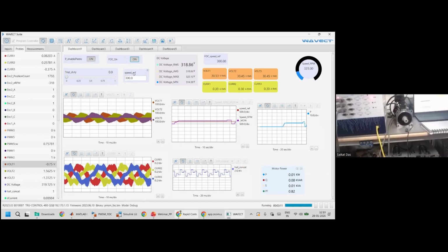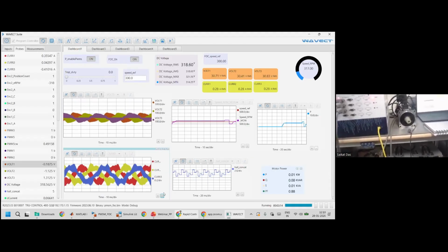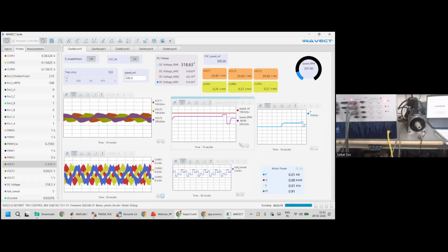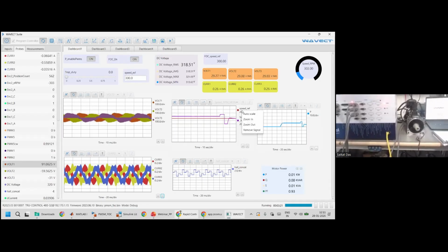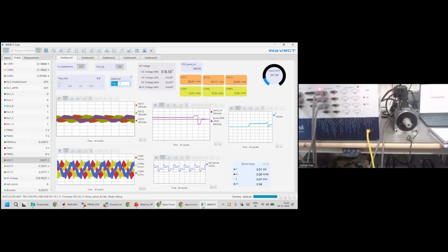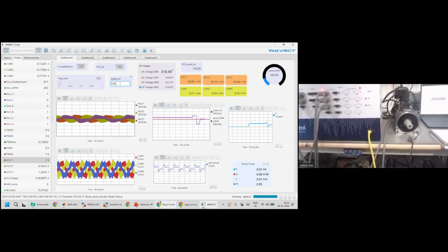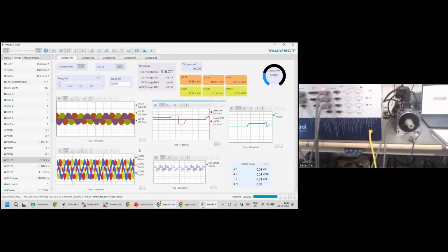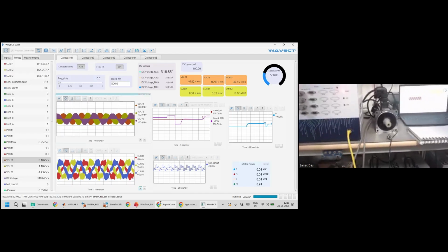So now let me increase the speed of the motor. Now I am entering the input speed of 500 RPM. Based on the 500 RPM, you can see my motor current also increased. That's the motor voltage waveform, and this is the pulse sensor concatenator. Let me run the motor at, let's say, 1500 RPM. Simply click on enter, and you can see whatever the reference speed I entered, the motor is following the reference speed. It is drawing that much amount of current.